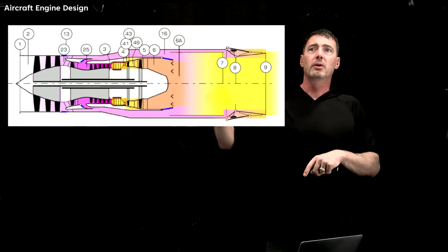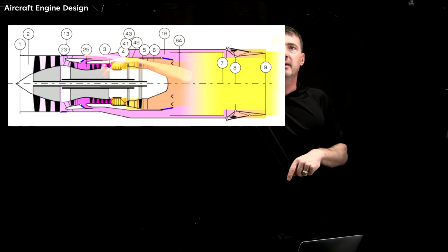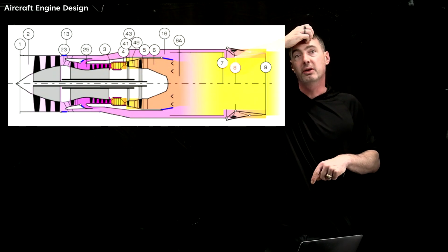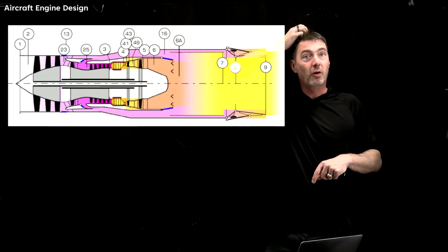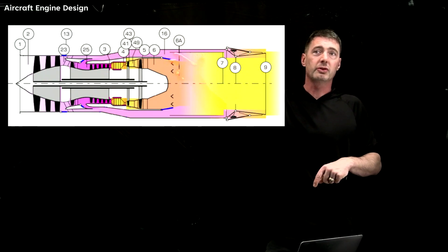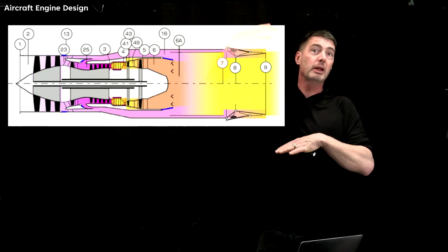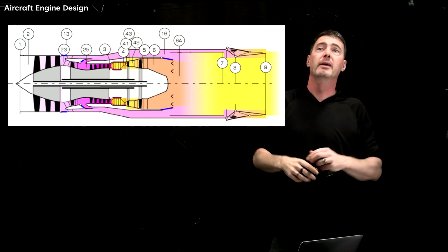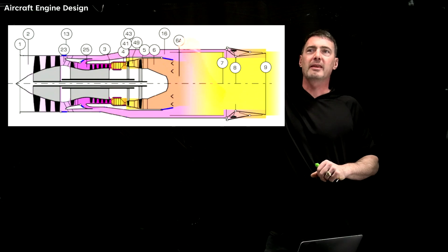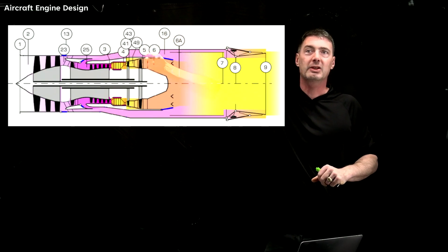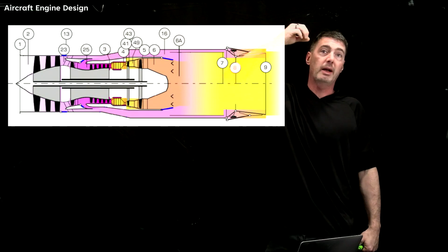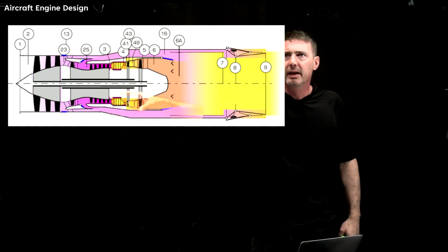Okay, and so the fan, this is now your bypass ratio. This is a pretty small bypass ratio, so this looks like a military engine. If this was a commercial engine, that fan would be really, really big compared to the core of the engine. Station 13 is not a 1.3, that's station 13. That's actually the bypass air of the fan, the fan air going around the engine.